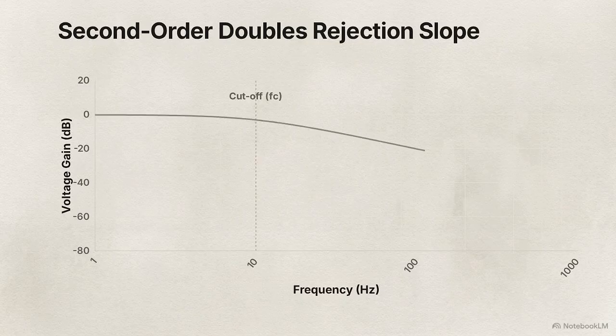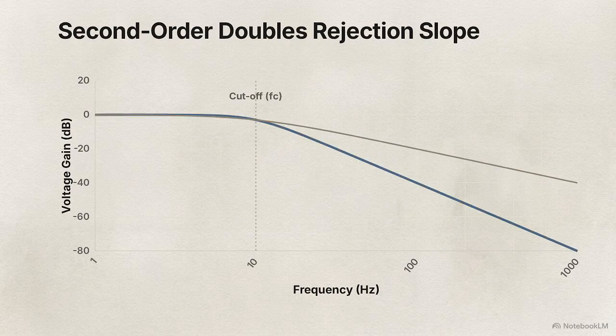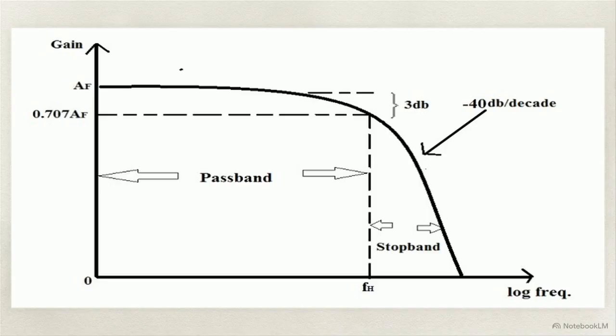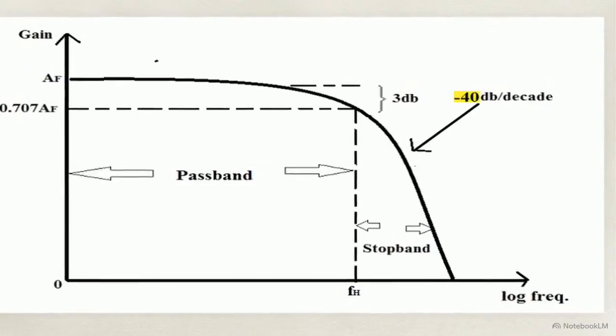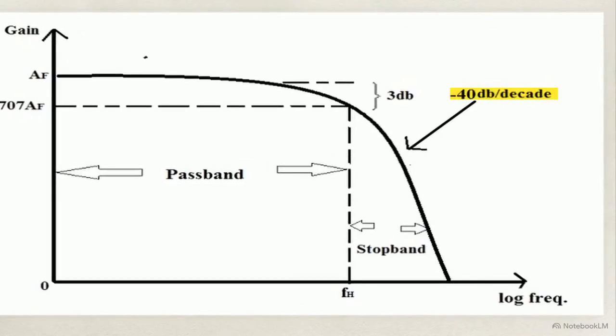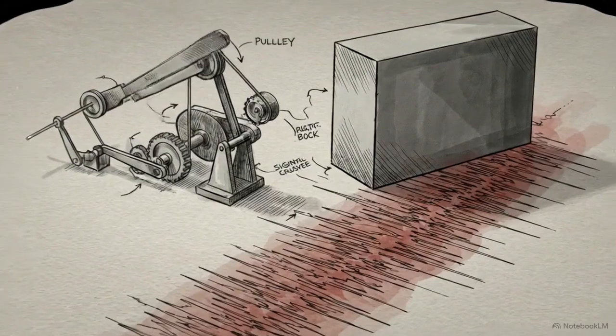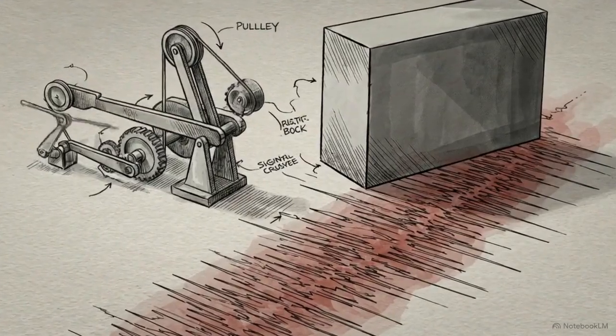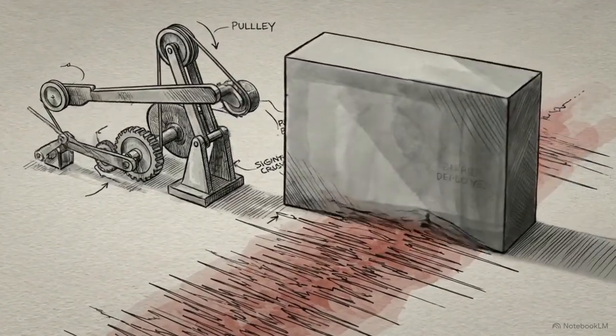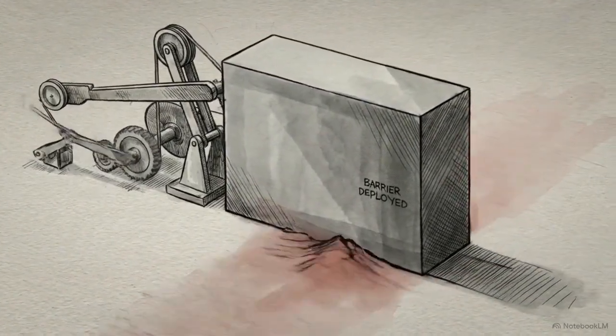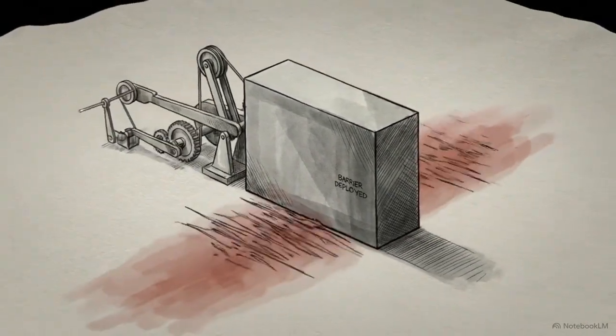Upgrading the circuit to a second-order filter exactly doubles the steepness of the stop band rejection. On this second-order response graph, the result is clear. The transition line plunges twice as fast, killing the signal at a rate of 40 decibels per decade. Filter order gives the engineer a mechanical lever. Stack more components, compress the transition band, and aggressively block any noise sitting near your target frequency.